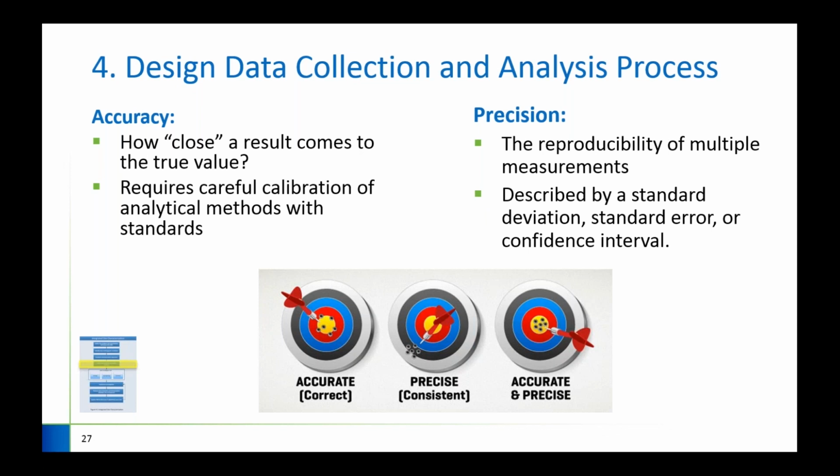When you're stepping through this process, I think our industry has come around to the idea that when you're in the characterization phase and you're trying to build your CSM, and you can use these real-time tools, profiling technologies, MIP, LIF, whatever, there's more value in generating a whole lot of screening level data than there is in installing monitoring wells and just sampling those. Again, when you're trying to characterize a site, you want to use site characterization tools. Monitoring wells are for monitoring remedies.